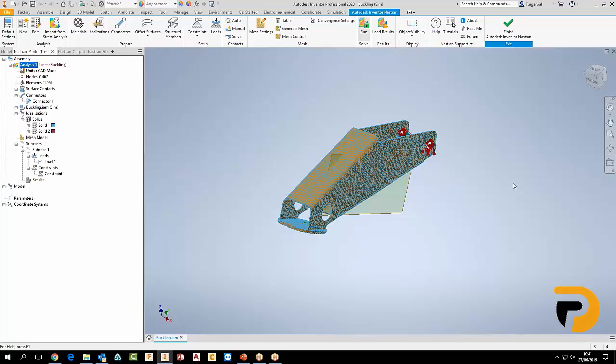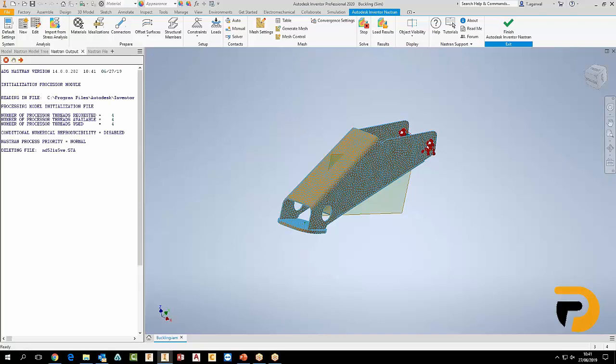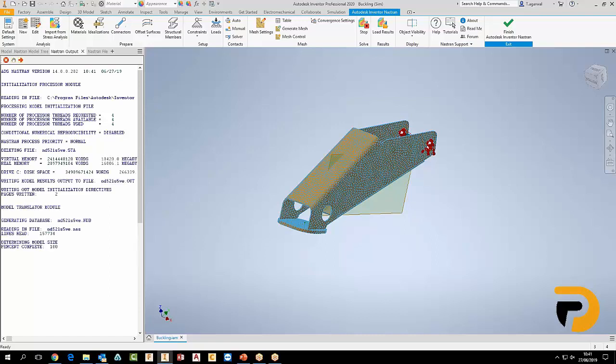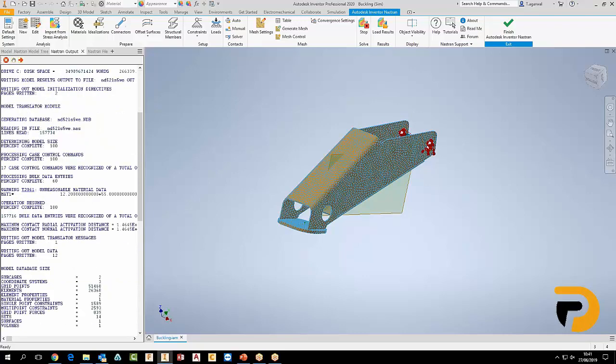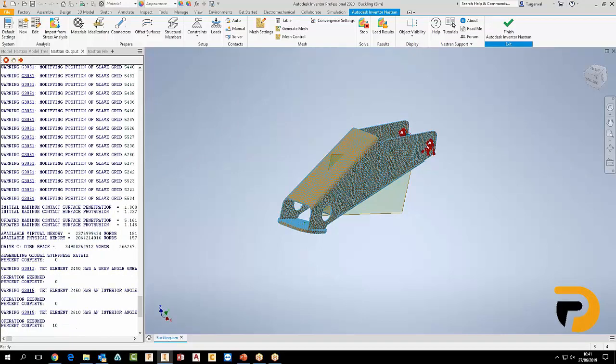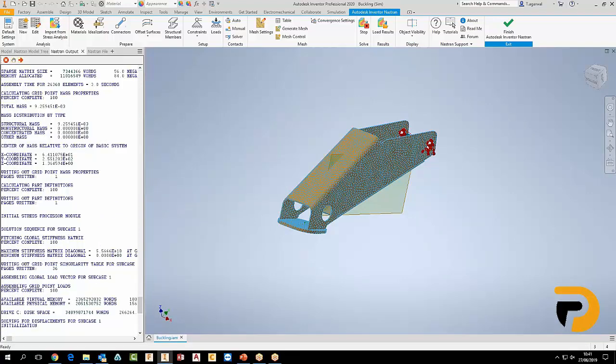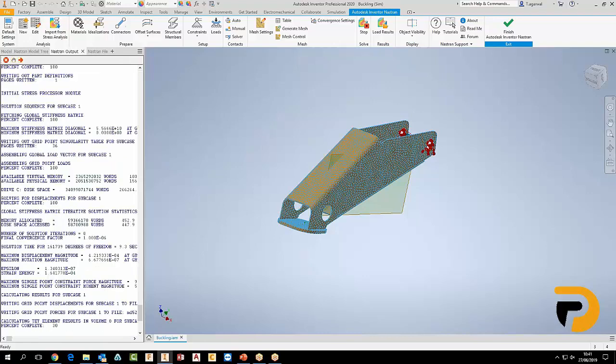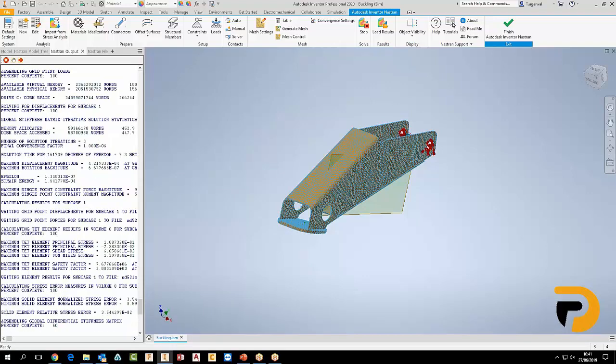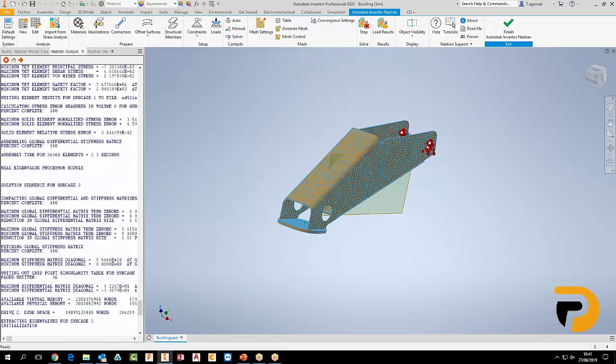Good to go. As we're running the simulation, you can see that it may take a while. Yeah. You can see very quickly, especially how we put in the connector at the end, how quickly we can constrain or fix multiple geometry without too much effort. Yes. In standard Inventor FEA, I would have to go into each one of those surfaces and fix those, select it manually and do everything manually. Or in an extreme case, if I wanted a really accurate result, I would have to include the shaft, then put in the contacts for the shaft, fix the model against the shaft, etc. So there is a time-saving element to all this.